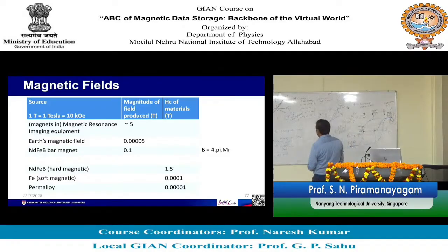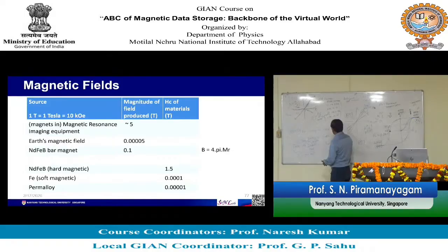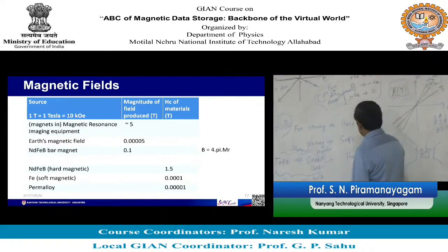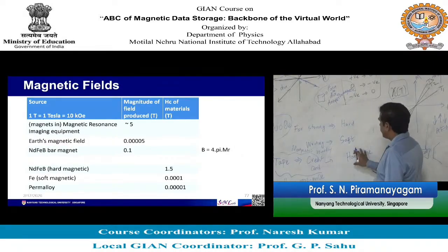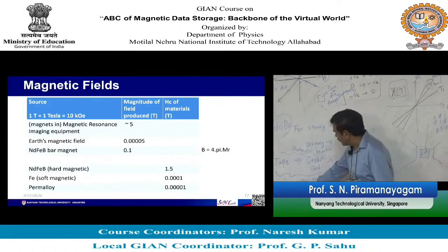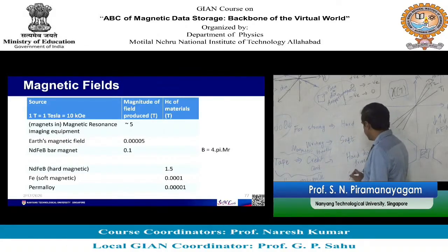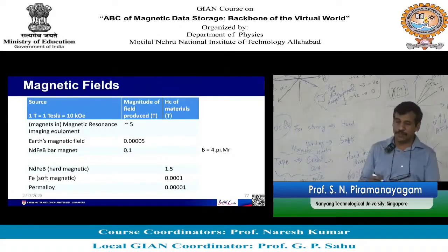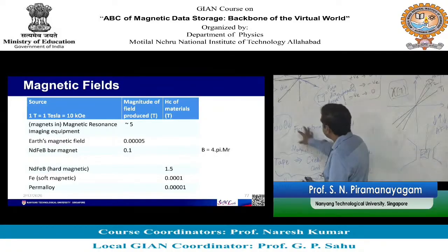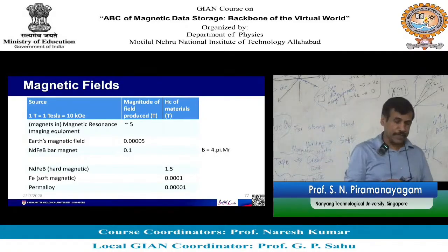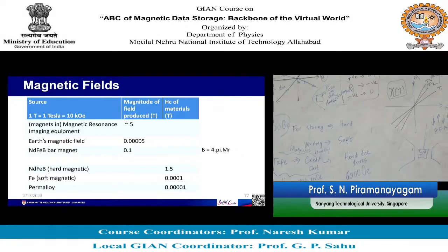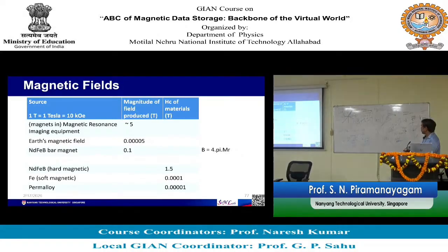But if you move on to the hard disk drives, I mean hard disk drives also long back had coercivities of these values, but these days the coercivity of hard disk drives is like 6000 or 7000 Oersted, much larger than the magnetic field that can be generated by a permanent magnet. So, usually permanent magnets won't erase the information of a hard disk drive.